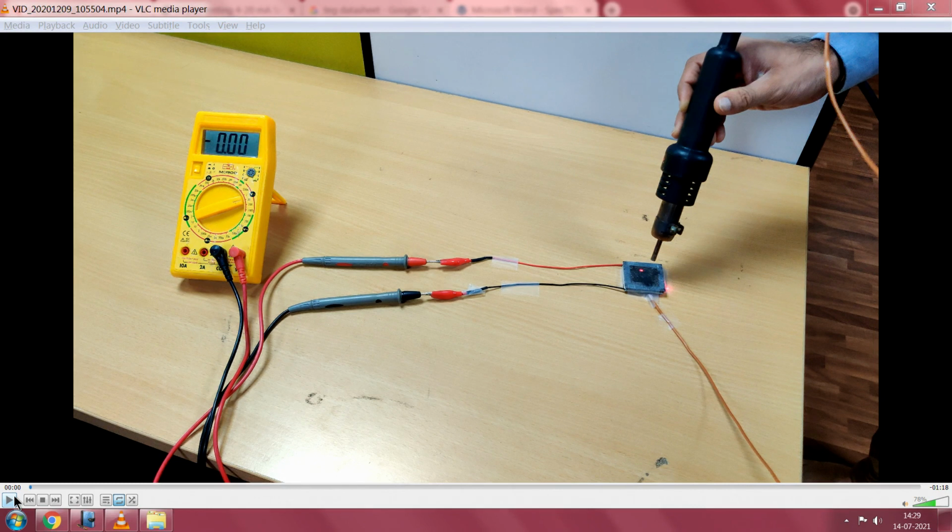What you see on the left side is a multimeter, which is essentially measuring the open circuit voltage. There are two probes, which we have connected to the TEG output. Here is the TEG. On top, our colleague has held a hot air gun, trying to heat that surface so that it creates a hot surface. Down this wire is the cold side, which is mounted to the table. So, it is fixed to the table and you are measuring the table temperature. In other words, the TEG is placed on the table and you are measuring the temperature of the cold side.